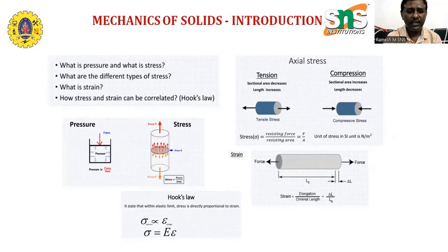Then we have another parameter called Poisson ratio. Poisson ratio is represented by the letter mu, or generally 1 by m; m is just a notation with no special terminology. How can we define it? It is nothing but the lateral strain to the linear or longitudinal strain when the material is stretched. The lateral strain by linear strain is generally given a negative sign.